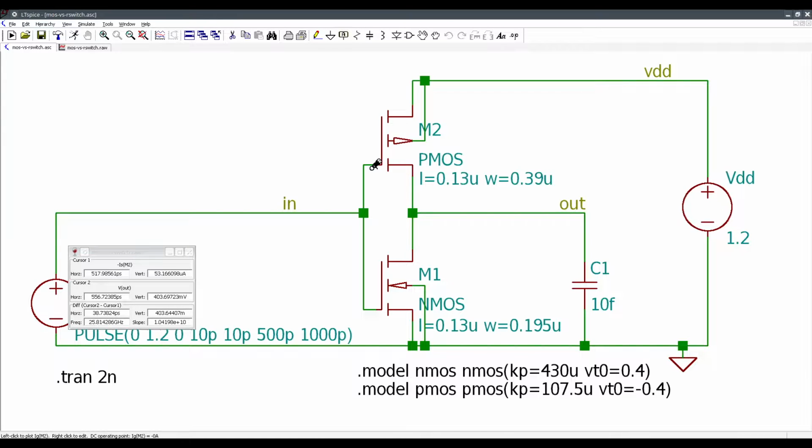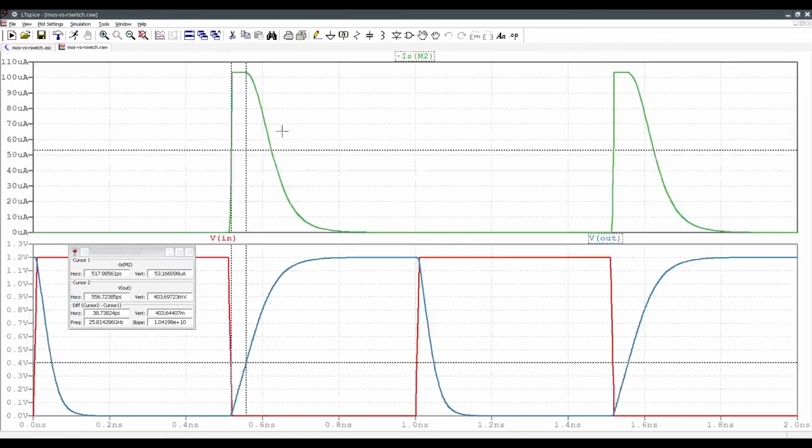The drain is higher than the input by 400 millivolts. If the drain is higher than that, that means the gate is more negative than the drain. As long as it's larger than the threshold voltage, I do have a channel on the drain side. This is a PMOS, so I need free holes in the channel. The gate has to be negative. It's always 0, which means the drain comes up. At 400 millivolts, we switch from saturation mode to triode mode.